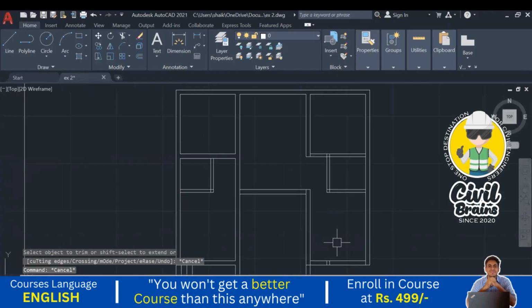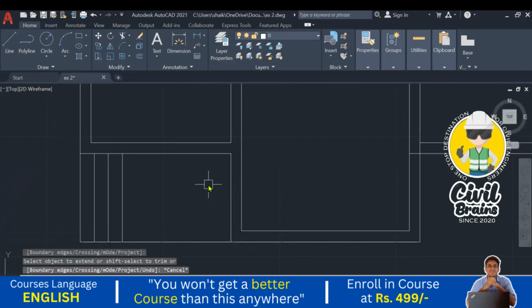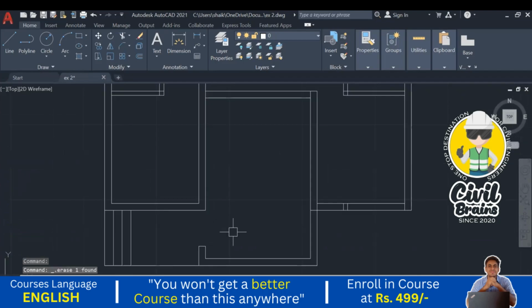It is like this only, right? Okay, just extend. Now we'll just draw the main door. Okay, offset 1.2 meter, press enter. 1.2 meter. Now just trim, and this extra one, delete that one.